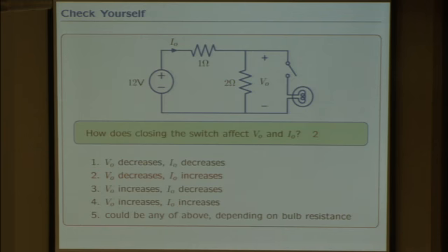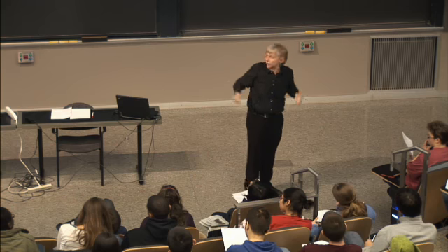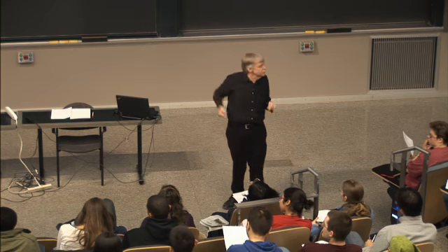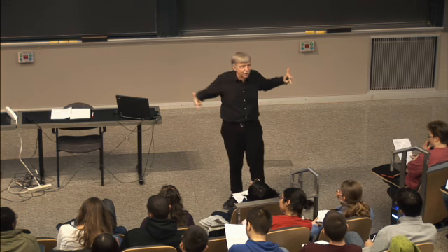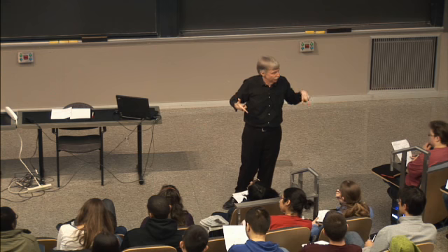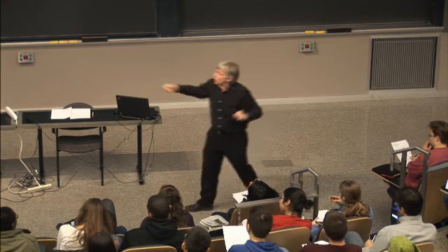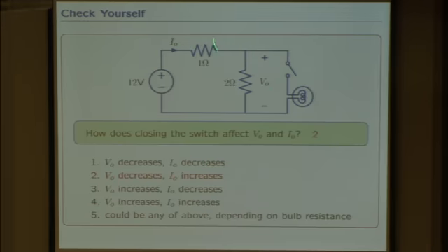The rule in a voltage divider is the same current has to flow through both resistors. If the same current flows through two resistors, then you can use the voltage divider relationship to see how voltage partitions between the two resistors. If current gets siphoned off the node between the two resistors, you can't use the voltage divider relation anymore. That violates the premise of the voltage divider relation. So when I close the switch, this is no longer a voltage divider, and it no longer works like a voltage divider.